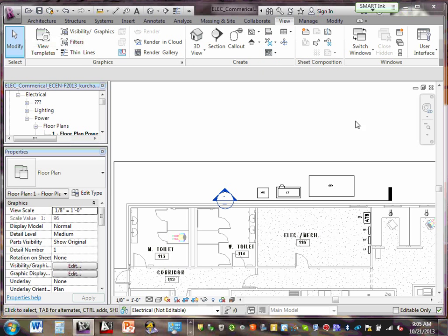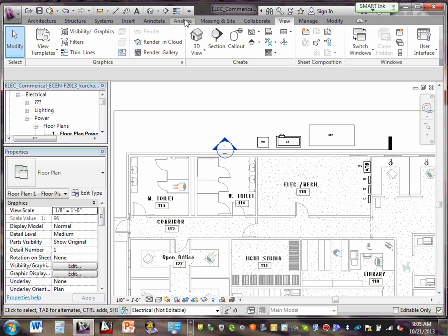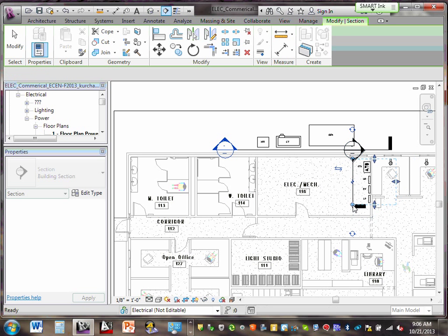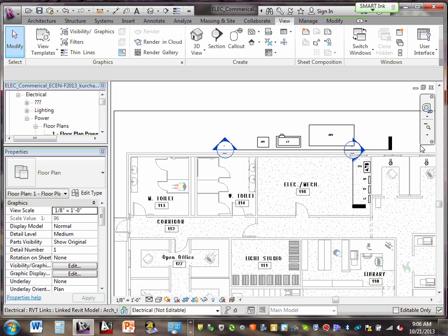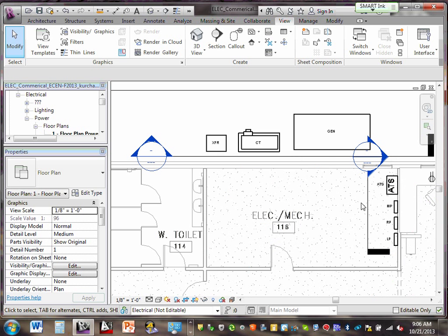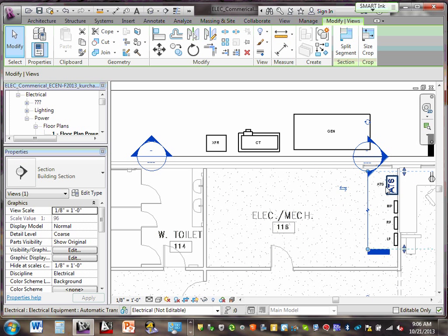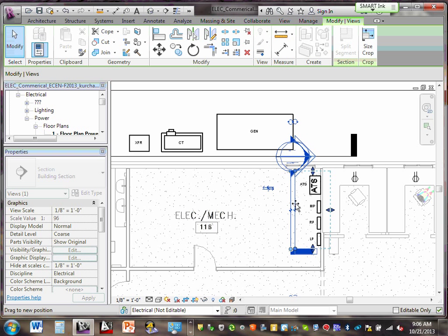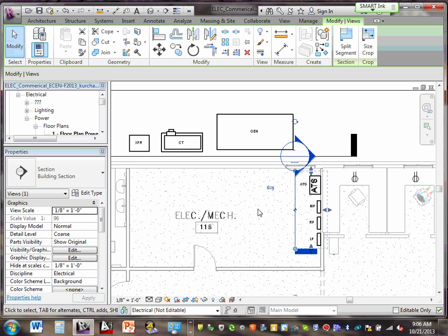So, okay, do me a favor. Go zoom window here, and let's go to section again and drag it. Here's what I want. I'm going to start with my section right here and right just in front of the equipment. Put my section in front of the equipment. Okay, zoom region, and I'm going to zoom into my equipment here one more time. Can you guys see my section here? My section right now is all over. All I need my section to do is to take care of my panels. So make sure your panels are included in your section.